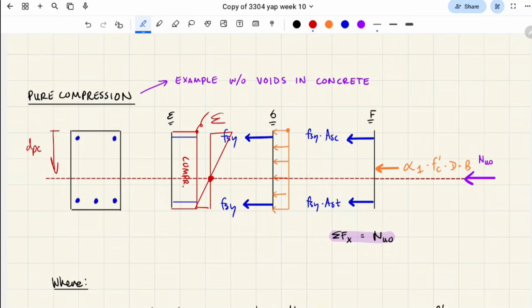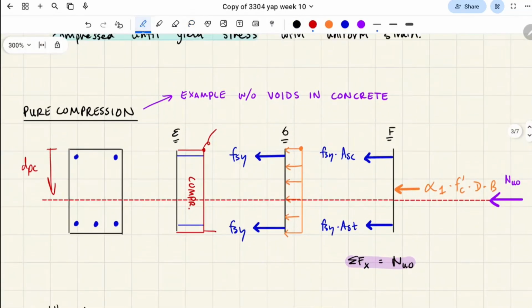If anyone remembers. Basically, for concrete to fail, for reinforced concrete to fail, the ultimate compressive fiber has to reach 0.003. That's the definition for all failure modes, including bending. And this was 0.003, if you remember this number. And now, same thing for uniform compression.